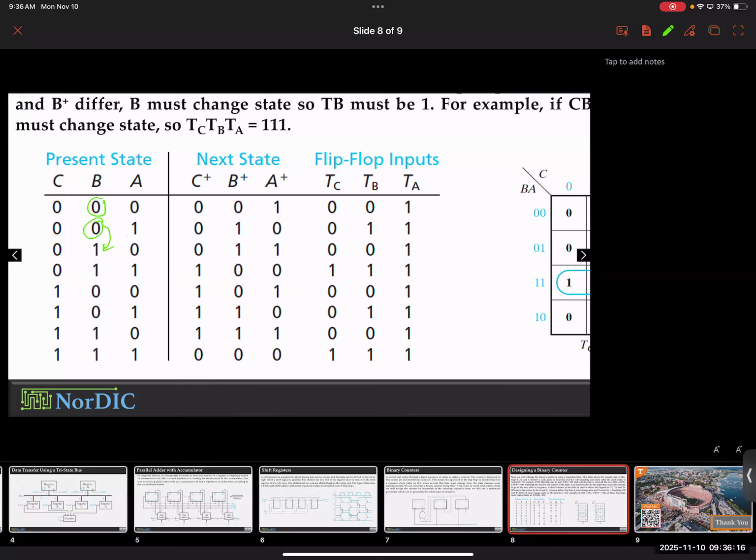Notice when it toggles, your first bit was on, or 1. Okay? And again, when did it toggle again? Here. When it toggled, your first bit was always 1. And again, it toggled here. And notice your first bit was always 1. Basically, you can logically think that when you add 1 to the first bit, you have a carry, and that's where the second one changes, right?